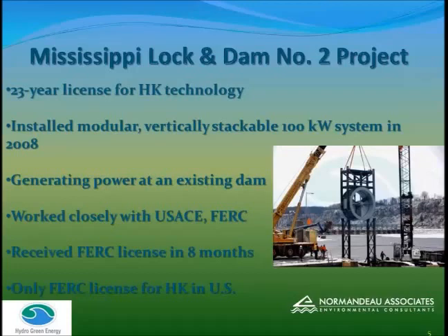This project ended up with a 23-year FERC license for the hydrokinetic portion of the technology. They installed a vertically stackable 100 kilowatt system. The actual output depends on the velocities in the tail race of the conventional project. Of course, they're generating at an existing dam, so no civil structures were needed for this.